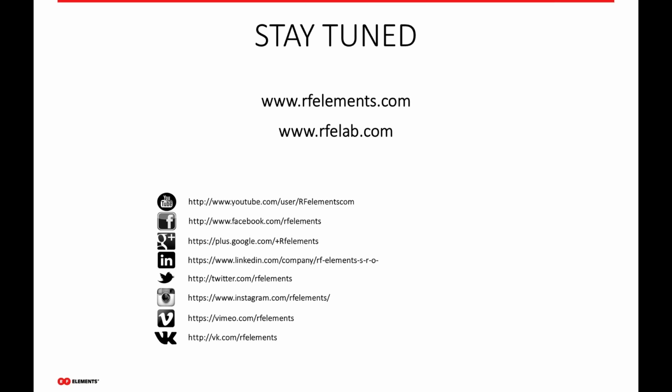You basically drop your pin where your AP is, you drop your second pin where your point-to-point or point-to-multi-point customer maybe is, and then we have sliders. First off, you can pick the antenna that you want, whether it's a 30, 40, 50, 90, even our ultra horn and ultra dish. You can pick the antenna type that you're trying to use. You then put in the TX power of the transmitting radios. You can also adjust the MCS rate.